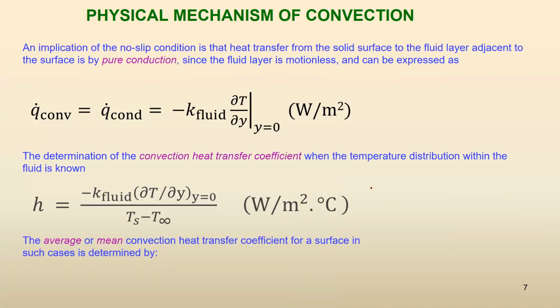So this is the equation. Since at the surface the fluid particles do not move, they stick to the solid surface, as I said, the mechanism of heat transfer is only conduction. Conduction inside the fluid, not the solid surface. Because inside the solid surface, obviously, we have conduction. So we can write the energy balance.